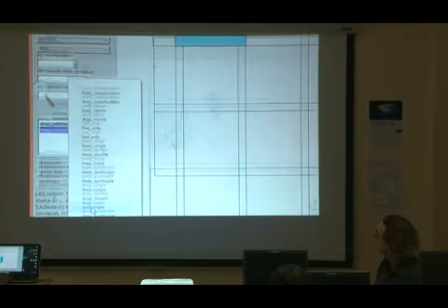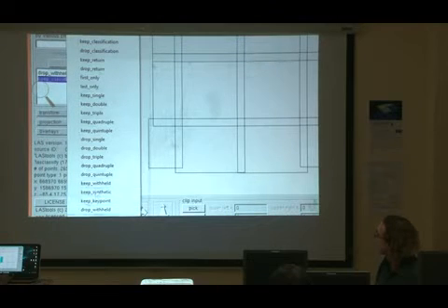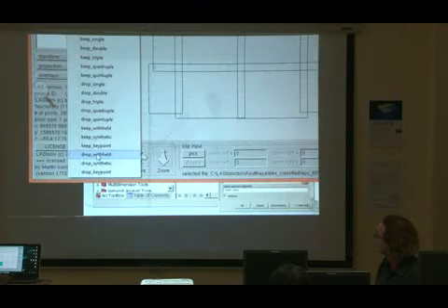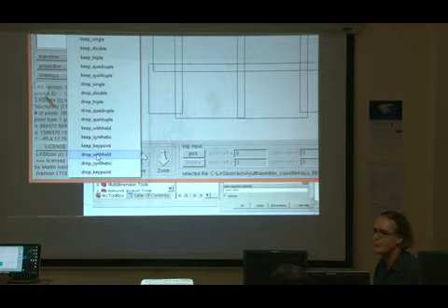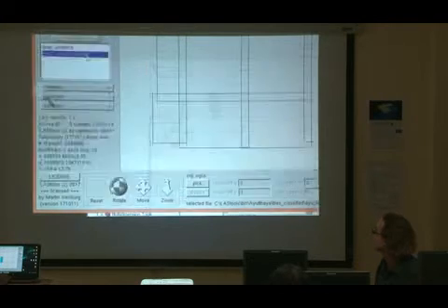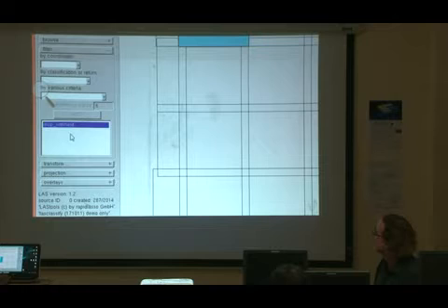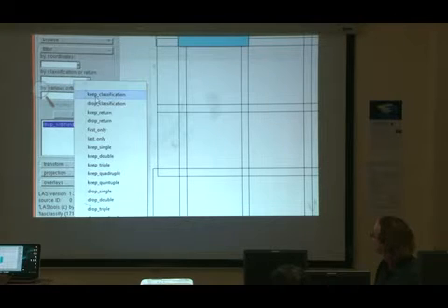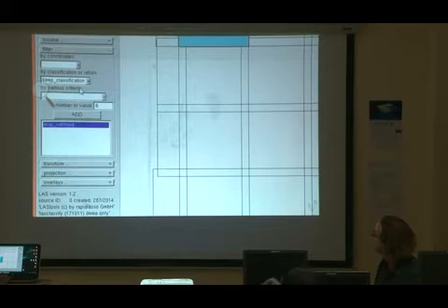Filter drop withheld is down here, drop withheld to remove the buffers because I marked all the buffer points as withheld. And I keep only the classification points. I keep only the points that are classified as buildings, the orange ones.